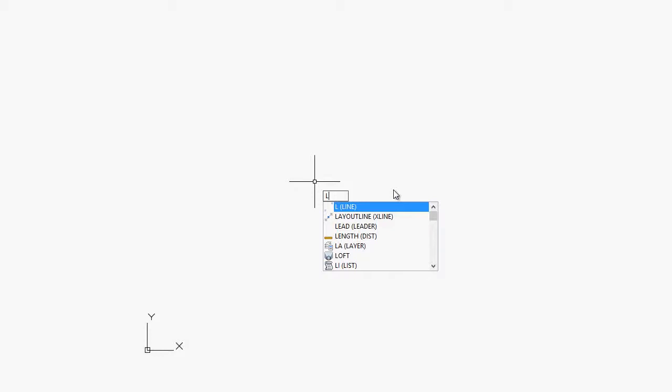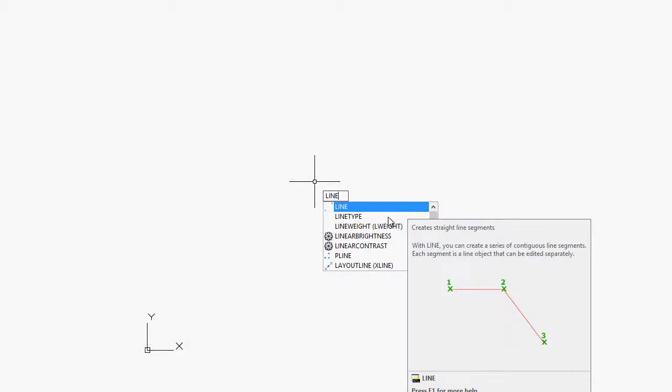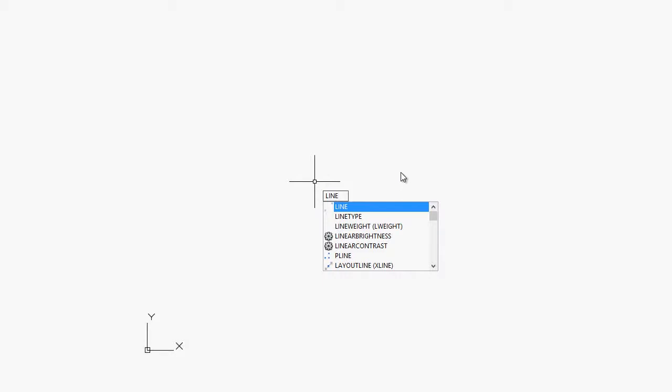I used to have a list when I first started out of these aliases and the commands that I'm using, just to keep a record. Otherwise, some of them are listed in the handout. This completion that they've added to AutoCAD is really helpful, because if you have to draw a line, obviously you think that typing in line is the most logical, but it also calls up other types of commands. So, for example, if line was not the command for line, at least you can go through a series of options to try to figure out what command you want to use.